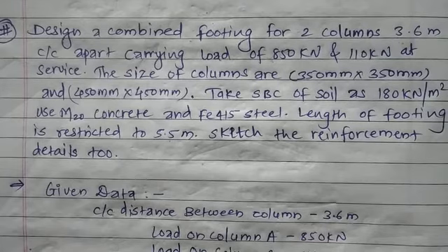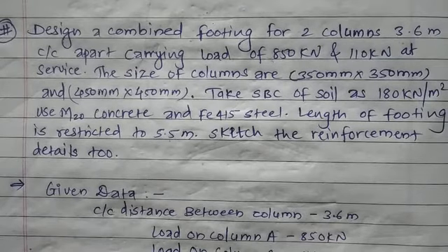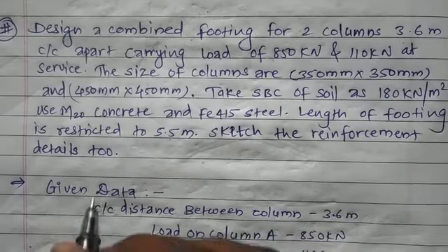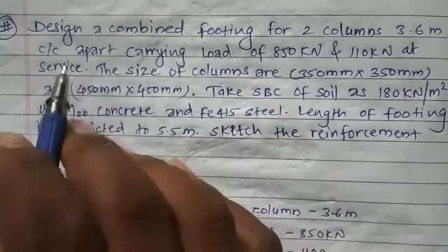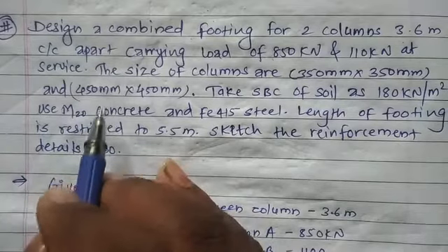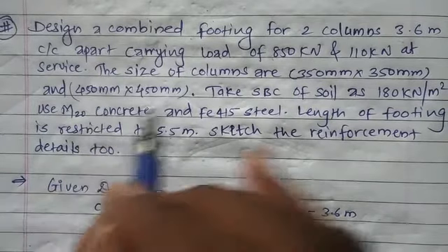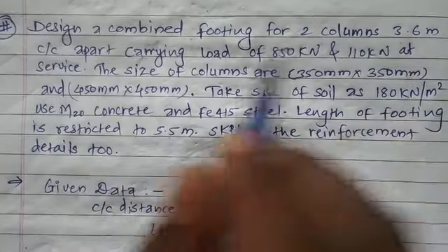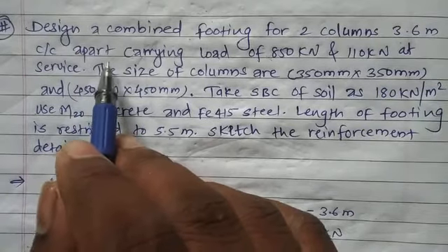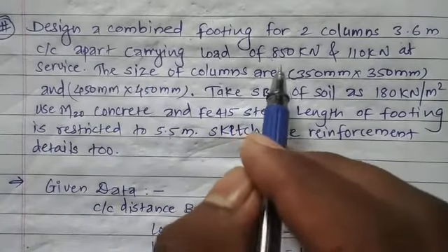Today in this video we'll start the numerical on design of combined trapezoidal footing. We'll start with the problem statement. Design a combined footing for two columns which are 3.6 meter center to center apart, carrying load of 850 kN